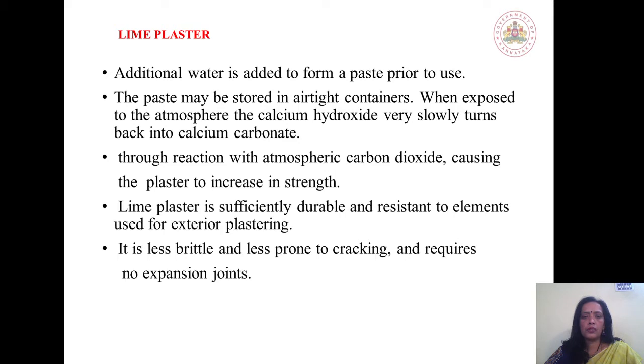When exposed to the atmosphere, calcium hydroxide slowly turns back into calcium carbonate through reaction with atmospheric carbon dioxide, causing the plaster to increase in strength. The lime plaster is sufficiently durable and resistant to the elements, so it is used for exterior plastering. It is less brittle, less prone to cracking, and requires no expansion joint. So these are the advantages of lime plaster.